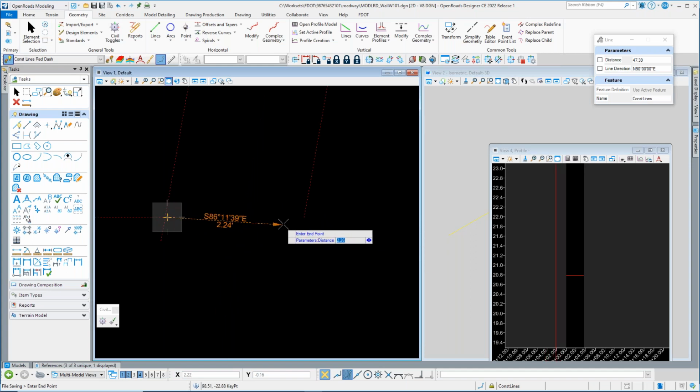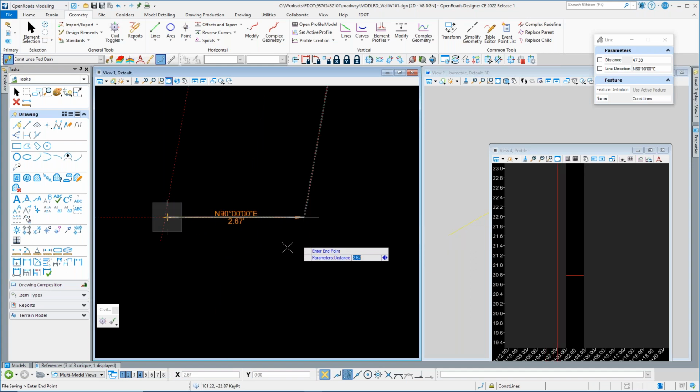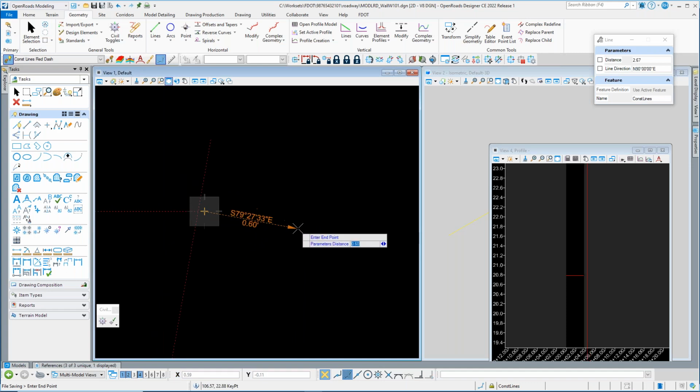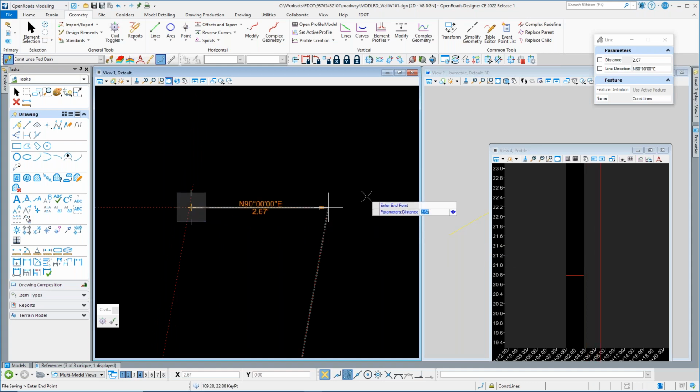There's a reason for that. It's all about lining up these edges and just snap to that new target that we just made. We're going to come up here to the left-hand side and do the same thing. We'll snap, set our origin, lock out our axis, key in the 0.04, and enter. It kicked us off just that little bit that we need again, and we'll connect these two.